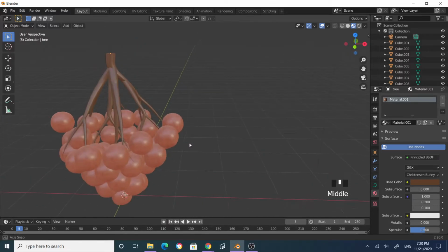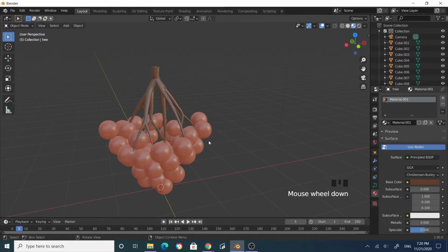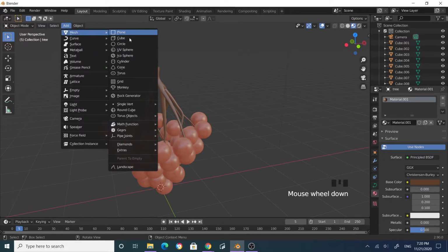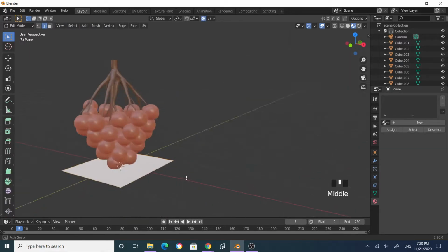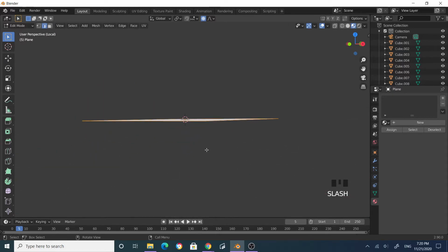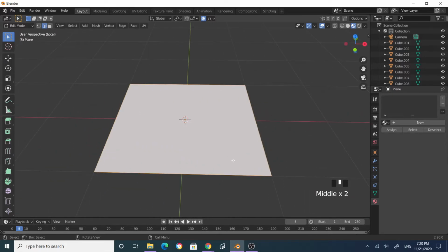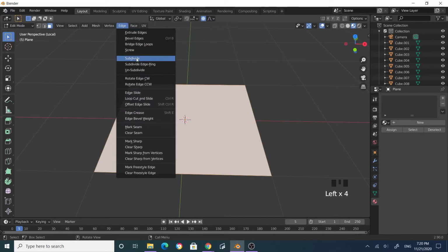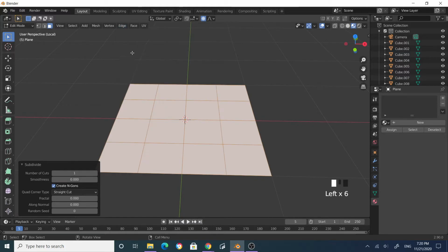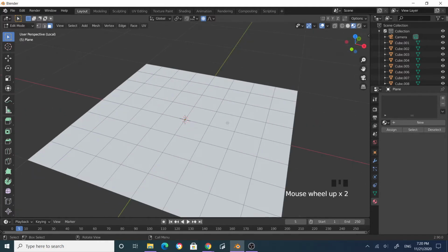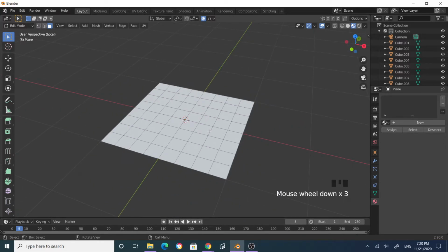A bunch of grapes. Now let's add a leaf. What I would do for that is add a mesh, a plane, and then Tab into edit mode and press / to go to isolation mode, local view of that object, and then select the face selection mode, select your plane, go to edges, subdivide, edges, subdivide, and edges again, subdivide multiple times. Okay, you can loop cut, but that's also possible.